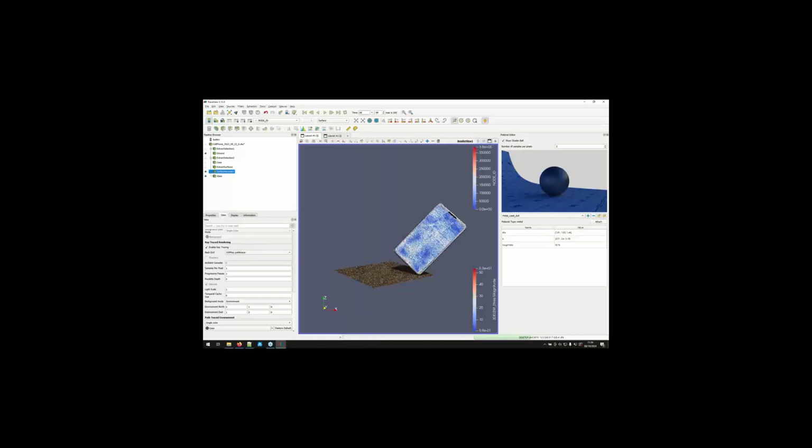Okay. François? Yes, we have a question from François also. Is OptiX included in the ParaView package, or does it have to be installed separately? Very good question. So in the official ParaView binaries, we ship OptiX. So it works out of the box. This is ParaView 5.13 that I just downloaded yesterday from our website. So yes. However, if you want to use, I don't know, maybe a recent version of OptiX and so on, you may have to build ParaView yourself. But by default, it's already packaged.